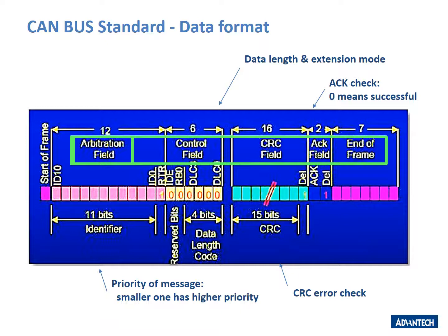This is necessary because sometimes several messages try to access the bus at the same time. Only one device can transmit at a time and the other devices will be in listening mode. The identifier is not defined by the CAN protocol. It is specified during system design and cannot be changed dynamically.